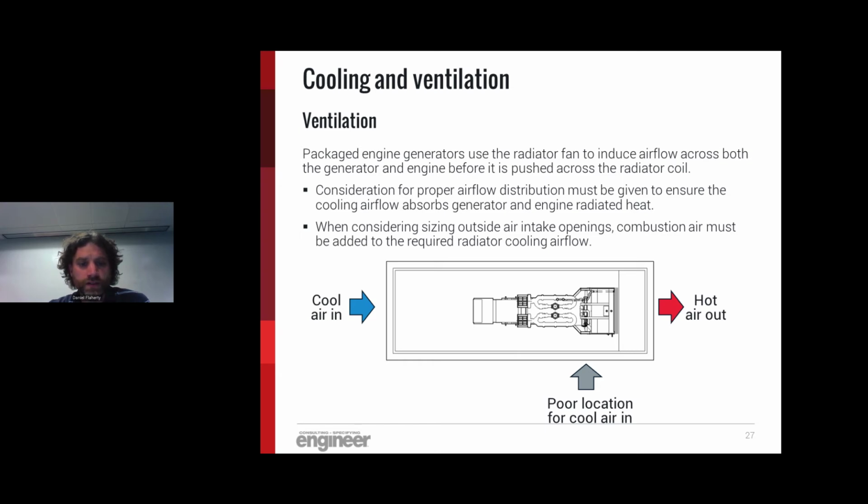Another consideration is the size of the air intake openings. You must also consider the combustion air to be pulled through those openings, to make sure that the fan in the radiator has enough capacity and static pressure to overcome that load.